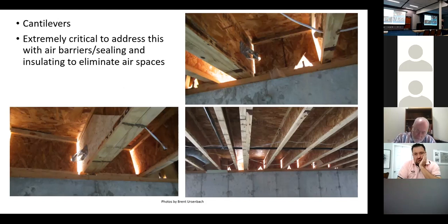Blower door testing has shown it's really not an effective air barrier. Air barriers need seams taped and stuff like that. And so I used to think 2 layers of building paper was pretty good, but I'm a firm believer in Tyvek and products like that, or other systems, you know, zip systems and stuff with tapes and stuff.